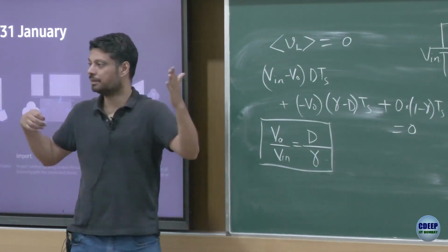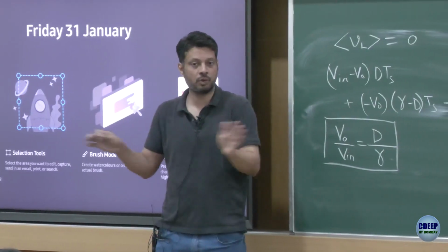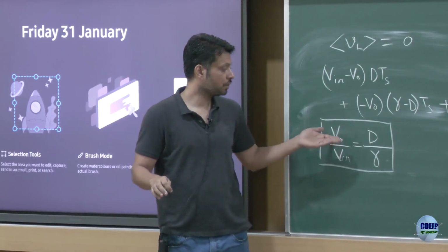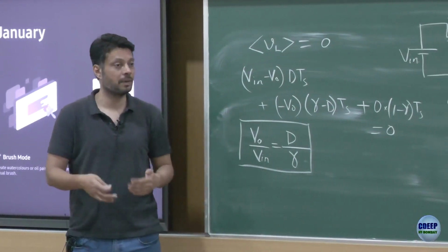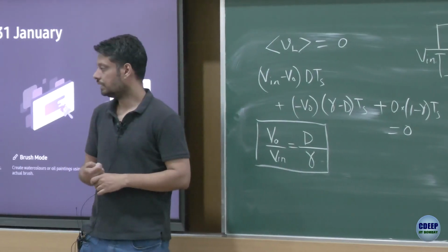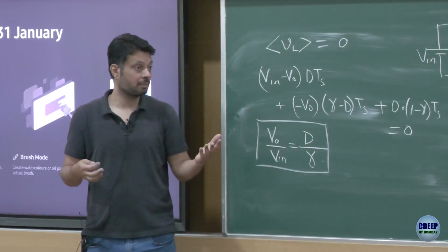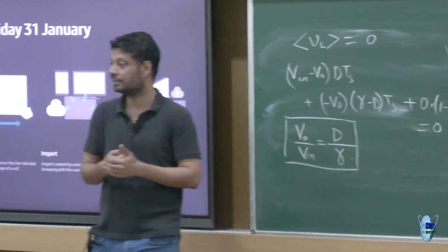So throughout CCM, your output voltage was more or less constant, but as soon as you reach DCM, your output voltage is going to change with gamma, and therefore you can no longer maintain a constant duty cycle, you have to keep adapting the duty cycle based on the load, right. Earlier also, in reality, there may be small variations, but not that much, but in discontinuous conduction mode, certainly you would have a large variation of duty cycle, isn't it?